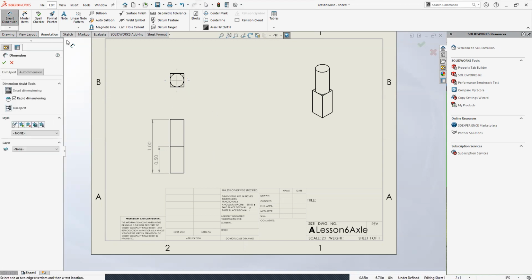I know sometimes it's tempting, oh, I want to save them the math or save them the work, but in a lot of cases, give them enough dimensions that they can make the part, because if you add too many, it can just get really confusing and sloppy.